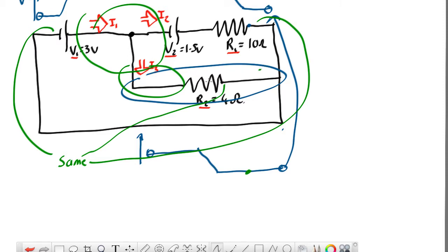If you've got the current flowing this way, the voltage drops from there down to there. And we know the voltage here must be lower than the voltage there because it's the case here. So that's consistent, and we've drawn the currents so that there's a constant current all the way around there. So there's also going to be I1 here, I1 there, this is going to be I3 through there, and I2 over here. We need to make sure that current doesn't go missing anywhere. So if you've got I2 going through here, it must be I2 all the way down there. If you've got I3 along here, it's also I3 over there. And the current into this junction has to equal the sum of the currents out.